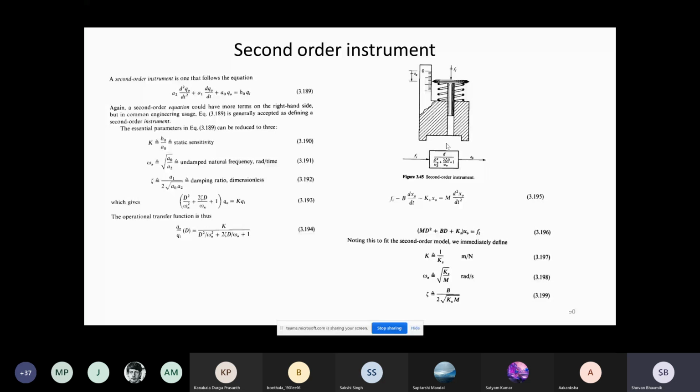So you can mark or calibrate the scale. If there is no force, the piston will not be shortened, so that point you mark at 0. Then you give different known forces, the spring will be squeezed, and you mark it. That becomes your calibrated instrument.